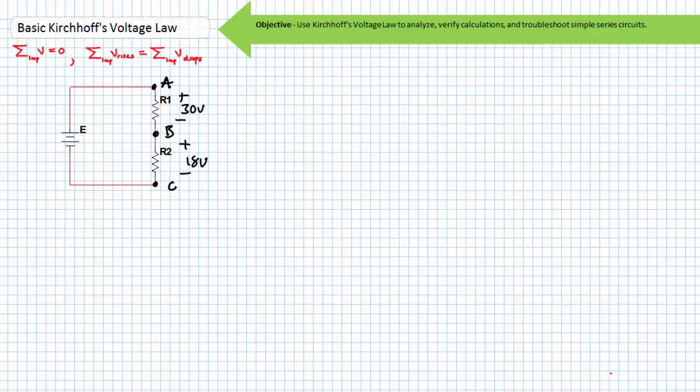A ground reference means exactly that. The voltages are simply referenced from ground. It's just a reference, and it is not essential to the functionality of this closed circuit. Node B is still 18 volts higher than C. Node C, for all intents and purposes, could be 5,000 volts or 5 kilovolts higher than ground. Node B in this case would still be 18 volts higher, or 5,018 volts referenced from ground.